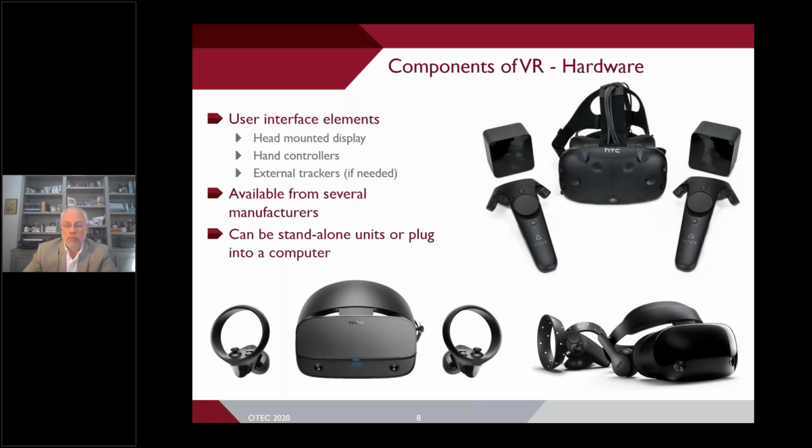One point I want to cover before moving on is the two major styles of HMD, because it will be relevant to the designing and planning of the driving simulator. The graphics processing for VR can either be done on the HMD itself, in what is known as a standalone unit, or on a laptop or desktop computer to which the HMD is connected, usually with a cable.